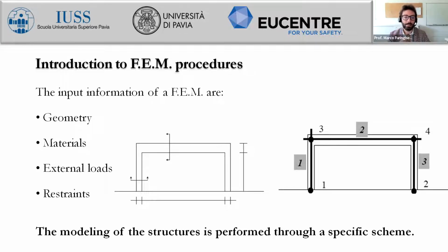And this implies that if we have a multi-story building, we cannot model a single frame element for the whole column for all the stories, but we have to interrupt the frame element at each story level. And this means that at the location of each story, we will have the effective connection between the beam joint and also the top joint of the previous story and the bottom joint of the subsequent story.